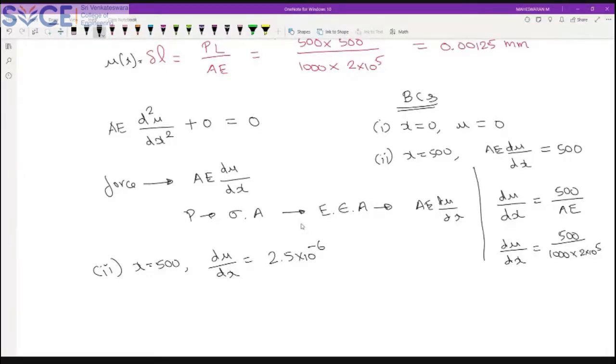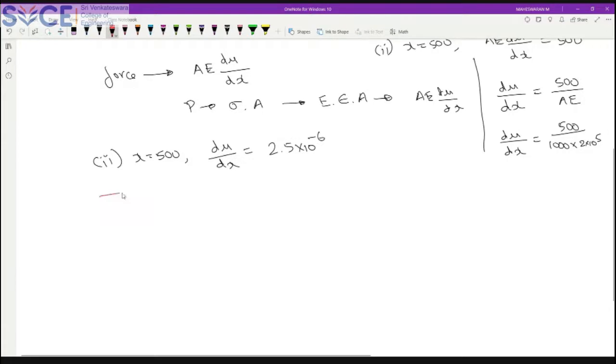So the next step is to proceed with our usual method. I have to take up a trial function. So let me consider what my trial function is. Trial function u of x is equal to a naught plus a1x plus a2x square. I'm not going beyond this because it will be a complicated one, right? So this is a simple problem. I'm going to take only one constant. Make sure I have only one constant.